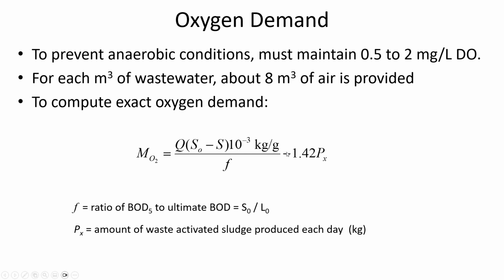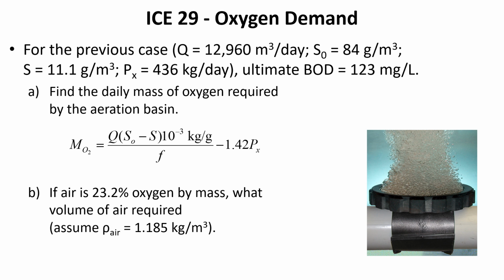And then you can see that we're subtracting the amount of sludge production from the oxygen demand, because if they're generating sludge, that's cellular mass that reduces the oxygen requirements, because this difference in substrate would be assuming that 100% of the oxygen demand went into just cellular activity, and the mass of new cells that are produced reduces the oxygen that they are consuming.